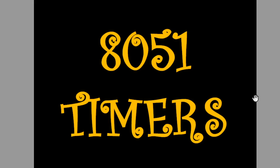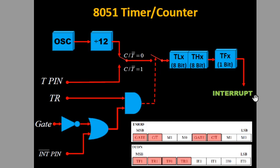So, 8051 timers. Timers are used to provide a specific delay, or a specific counting event can be performed using the 8051 timer. They are individual, independent blocks which run along with the crystal frequency as well as with an external frequency. So there is a structure for this timer. This is the internal structure of an 8051 timer.